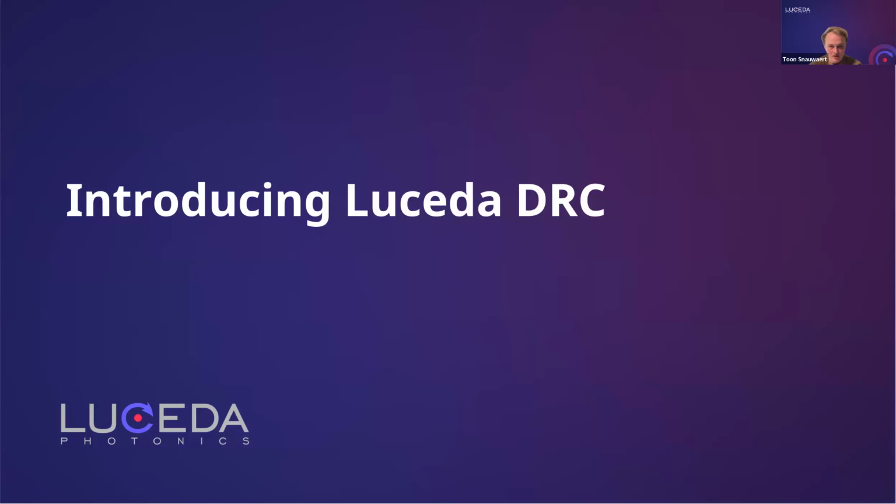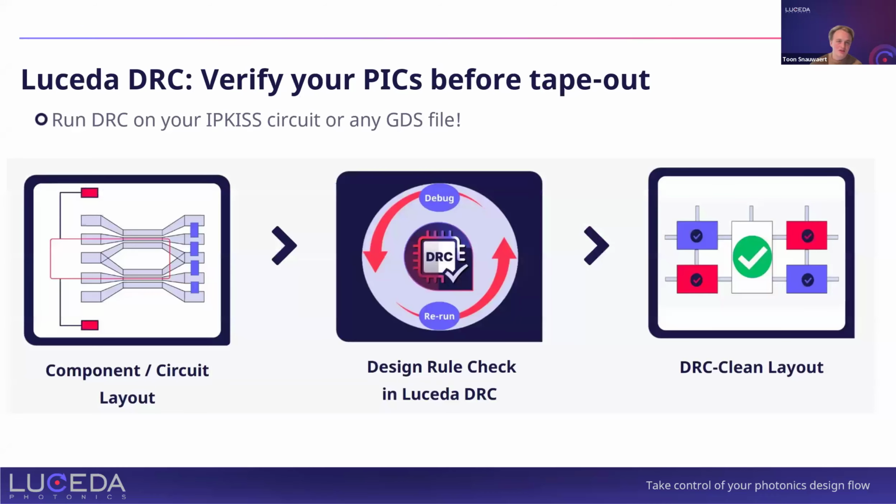So with that in mind, I would like to introduce Luceda DRC, which is a new product that we've offered since March. With this new tool, you are able to verify your PICs before the tape-out by running a DRC check. And you can run a DRC check on any component layout, circuit layout, or even on any GDS file. When you run the check, you get a DRC report with all the violations. Afterwards, you can debug them and rerun the check until you end up with a DRC clean layout.